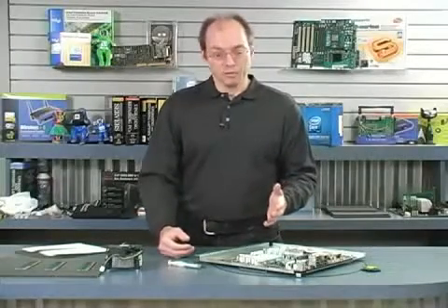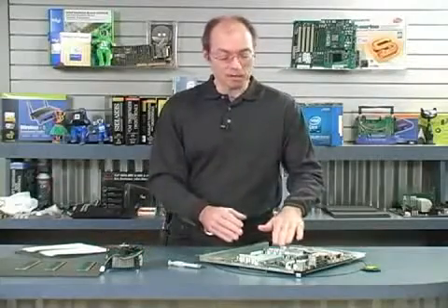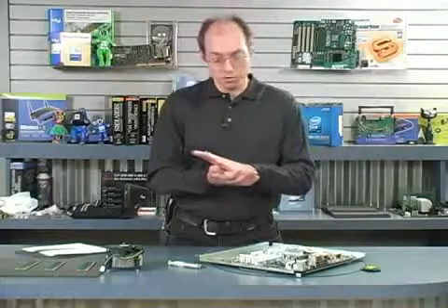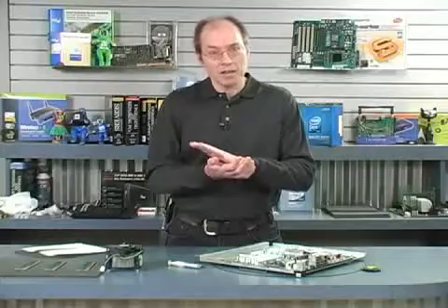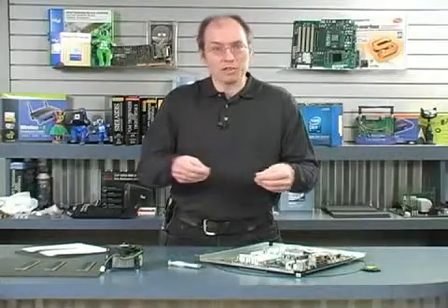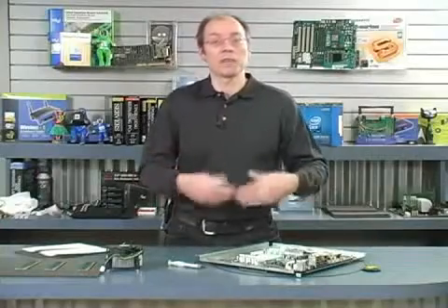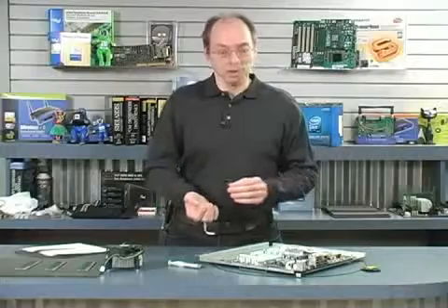Pump out refers to the fact that as the heatsink sits on top of the processor, there is slight movement due to different thermal coefficients of expansion and contraction, and vibration, and eventually this movement pushes the grease out. It extrudes, it oozes out from between. So eventually there's an insufficient amount in there.